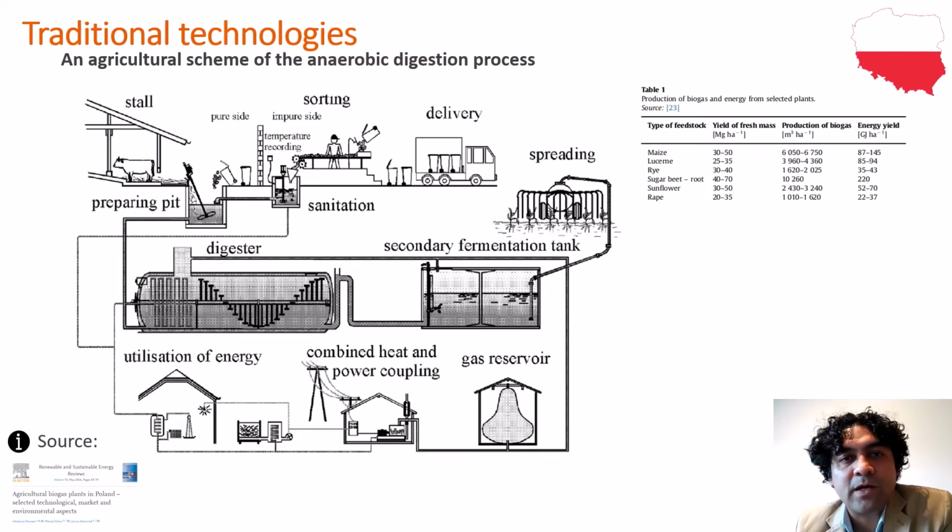The type and amount of substrate and the conditions of the process are determined already at the stage of designing a biogas plant. This is important in terms of technical aspects, including the size and type of the digester chamber. It is assumed that a digester chamber with a volume of approximately 50 to 150 cubic meters is suitable for small agricultural holdings.